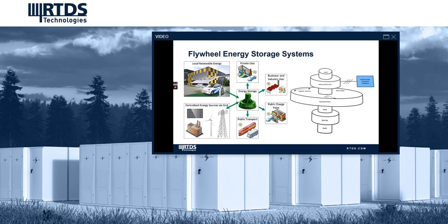Flywheels are typically housed in vacuum enclosures with magnetic bearings. This allows the flywheel to keep its rotation without requiring additional power for energy conservation. Flywheels can be used for fast charging of battery storage systems, uninterruptible power supplies, voltage, power, and frequency regulation for renewable energy, and in electric transportation such as ships, electric vehicles, and trains.